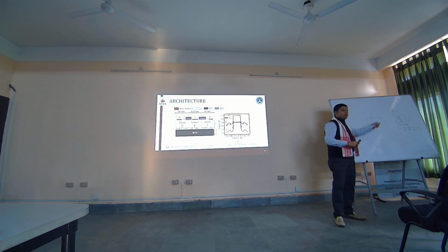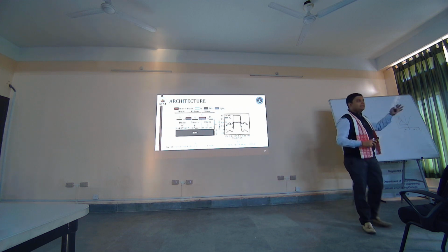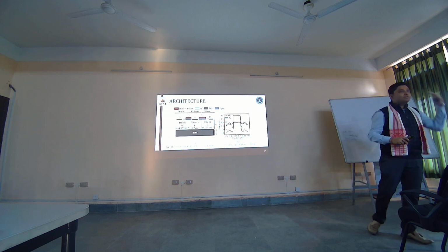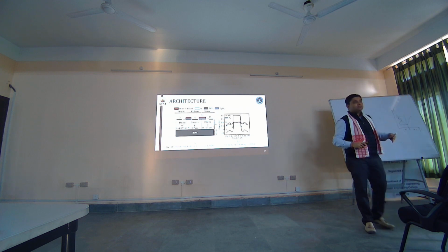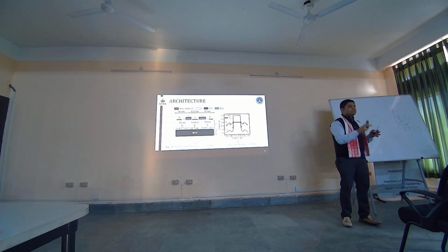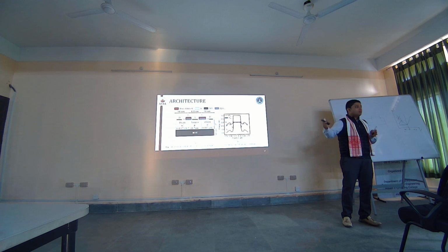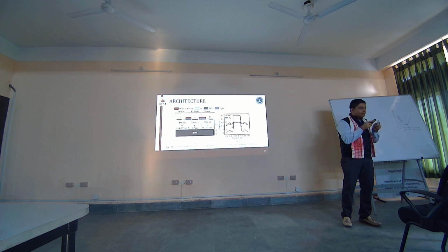If you want more functionality on your die area, it means you will need more drive current, so that using fewer devices you can drive more functionalities. So if I come down to one device unit, if it was earlier producing say 2 milliamperes, I will now need 4 milliamperes. Right? So that is how Moore's law is governed.